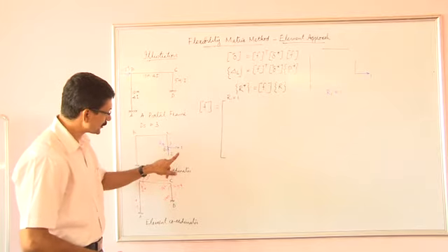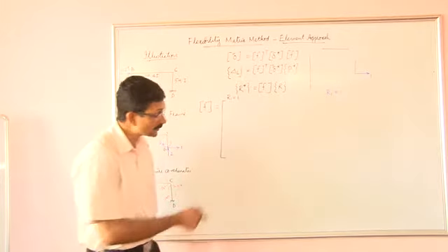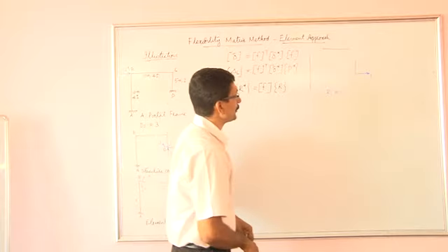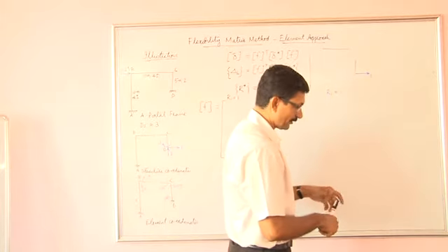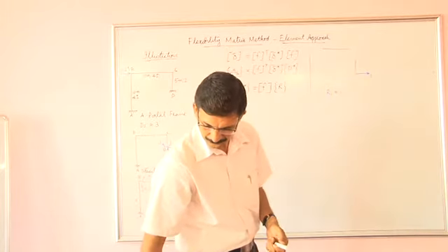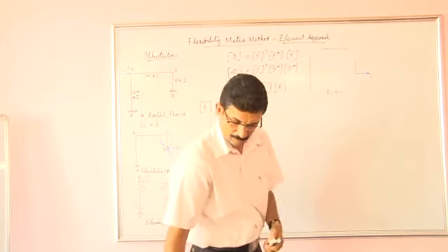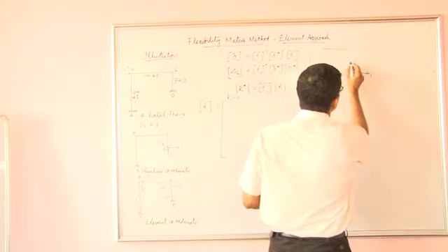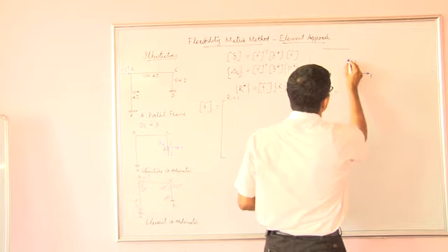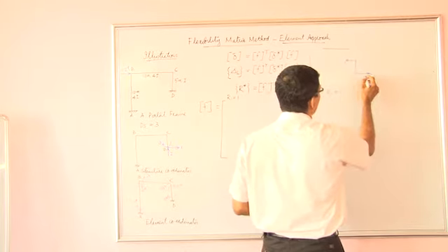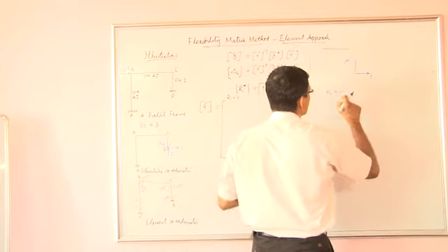Now if I put R1 equal to 1 as it is given over there, and if you draw the free body diagram of the 3 parts of the structure, we are going to get, for force equilibrium, a force over here which is equal to 1, and for moment equilibrium, this span is 5 meters.